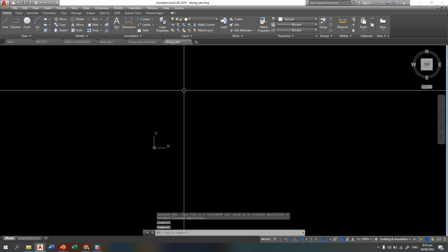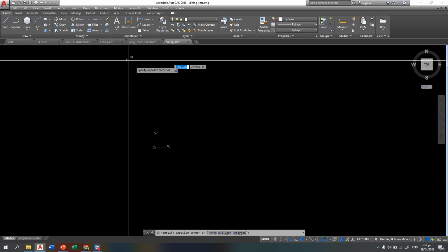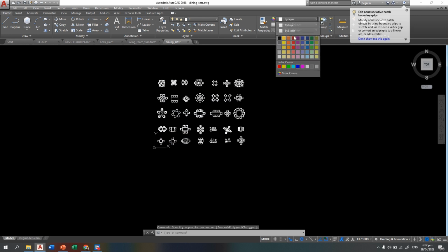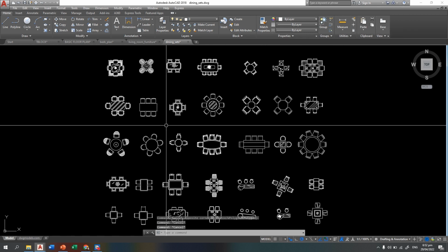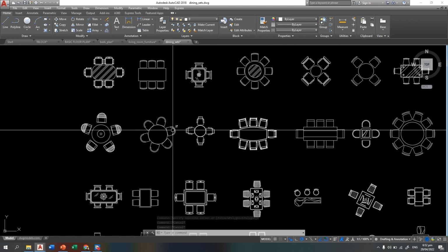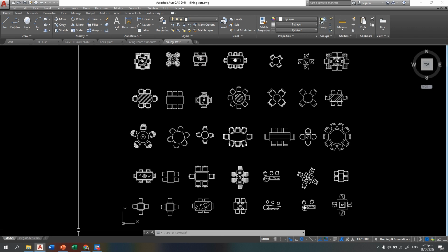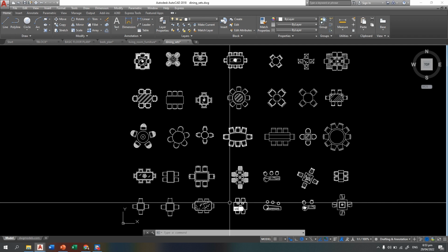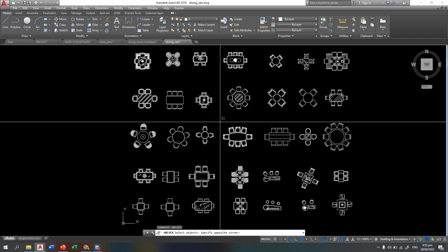Open that one. Then the furniture is somewhere here. Since we are using a black background, you can select this entirely and change the layer to bi-layer. You can choose whatever dining set you want and you can W block it, then you can insert it on your basic floor plan. Let's say this one.